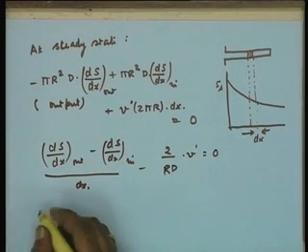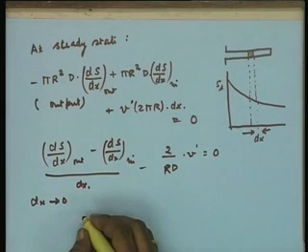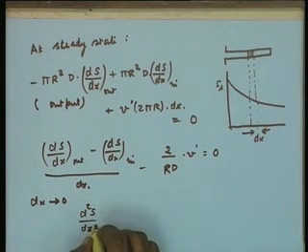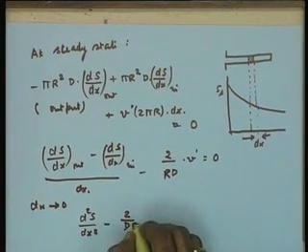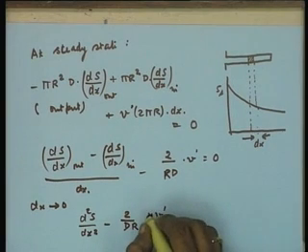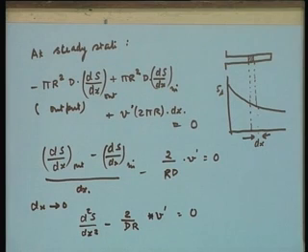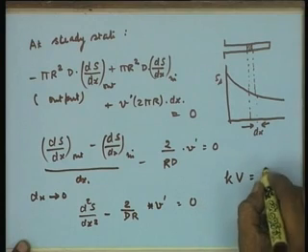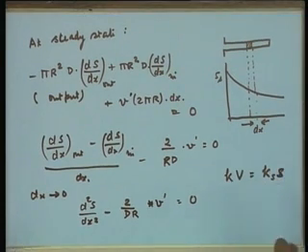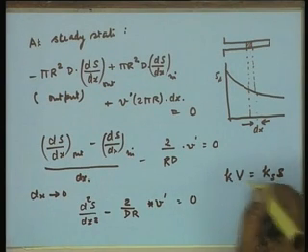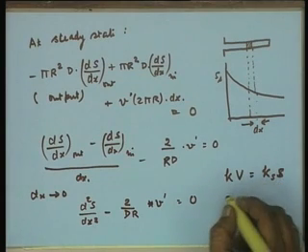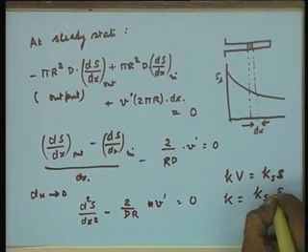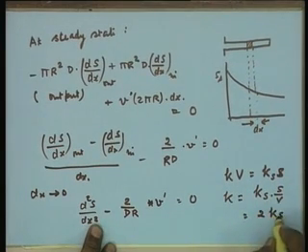Now if you take the limit as dx tends to 0, you can write simply a second order differential equation: d2S over dx square minus 2 by D into R into V dash equal to 0. This gives you a generalized second order differential equation which can be set for internal pore diffusion cum biochemical reaction. Here of course you can also make a modification. If this reaction velocity you transfer into volumetric form, there are two rate constants, k and ks, which could be zero order or first order, based on volumetric and based on surface area. For a cylindrical pore, k will be equal to ks into S upon V, and that is equal to 2 ks upon r.